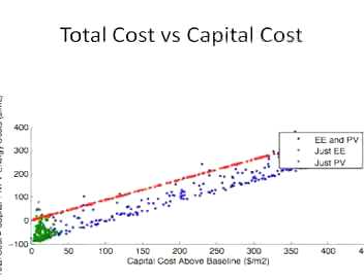We can also look at this in terms of total cost. So this is the capital cost plus a net present value of the energy cost over the lifetime of the building. Again, zero is our starting point. And again, you'll notice with some energy efficiency, the total cost goes down because we're saving so much over the lifetime of the building, it more than offsets the capital cost. Whereas if I purely do photovoltaic, we're going in the other direction.